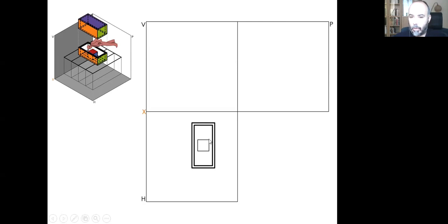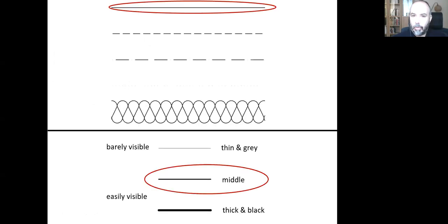So we can draw it again by using the exercise 7 dashed lines. However, this time we are seeing the object itself. So we need to use the continuous line, not the dashed lines, in order to indicate that it is something that we see, that is not something that has been cut by the plane.